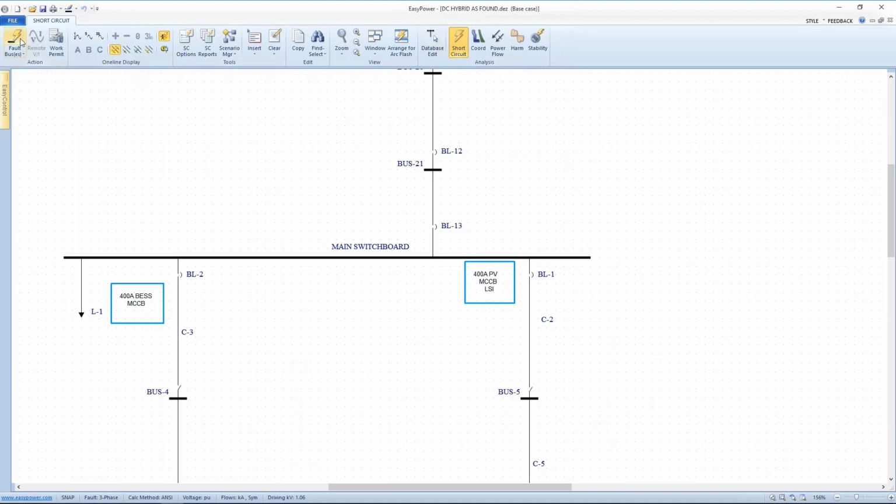If we go to short circuit focus, fault the buses, and look at the incident energy, we can see it's huge. And for a 600 volt system with a maximum of 400 amps in each leg, it doesn't make a whole lot of sense. If we look at the currents involved and fault this bus, we see 49,000 some odd amps coming from the utility, and then 460, 470 coming from the downstream loads. So right away you can see that something's not quite making sense.